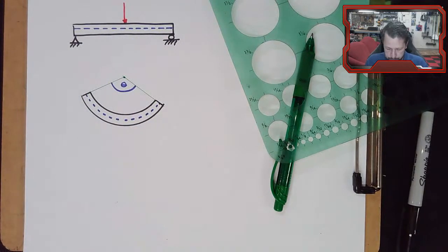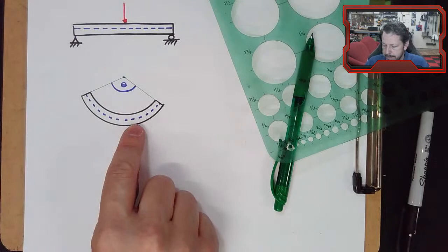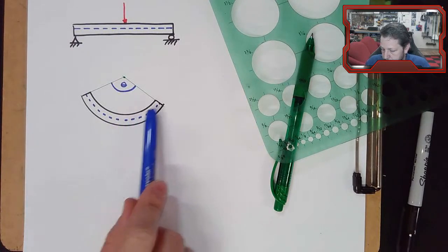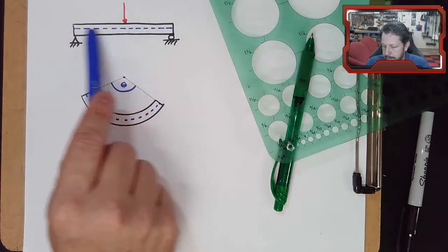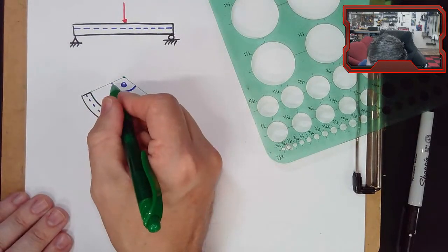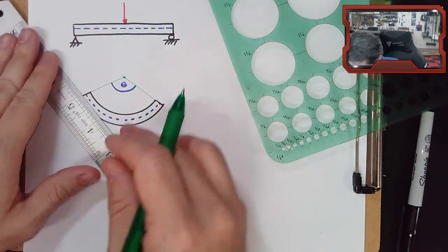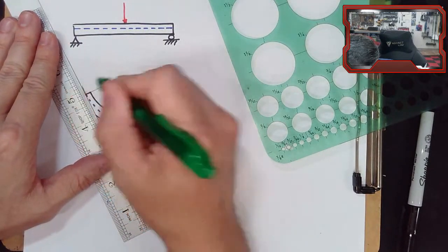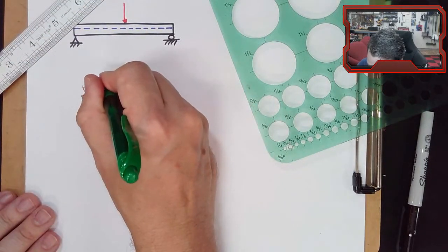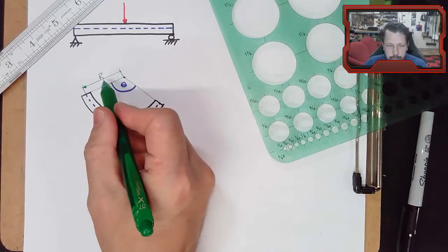It has the same length, because remember, the deal with the neutral axis is it is the point where there's no flexural stress. So if there's no flexural stress, then there's no flexural or axial, in this case, strain. If there's no stress, there's no strain. And so this blue line, even though it's curved, is the same length as it was originally. So that's going to be important later on. I'm going to give the distance from here to our center the label r. So it's a radius. This is the radius of curvature.